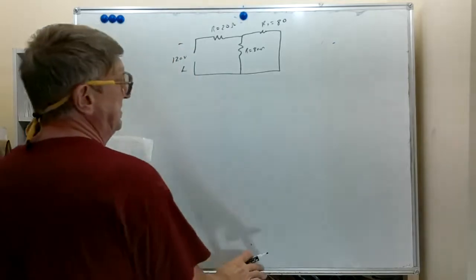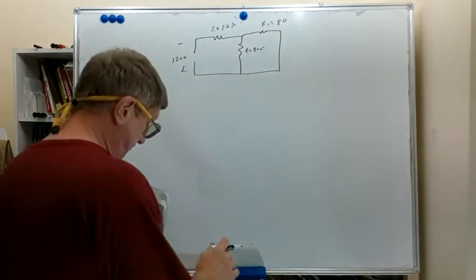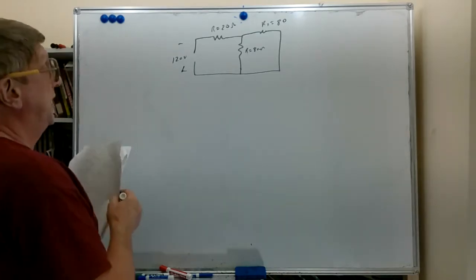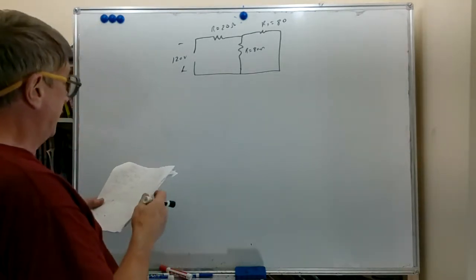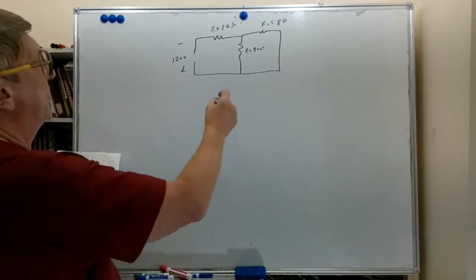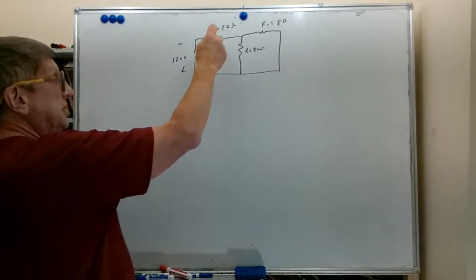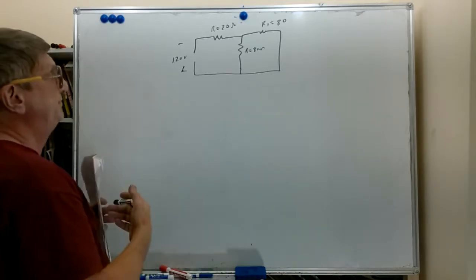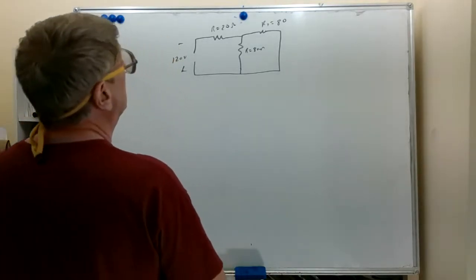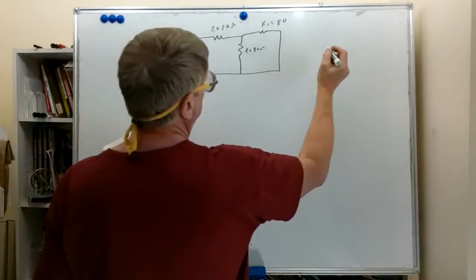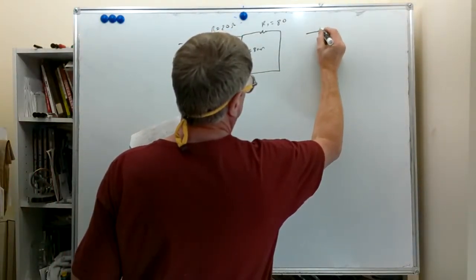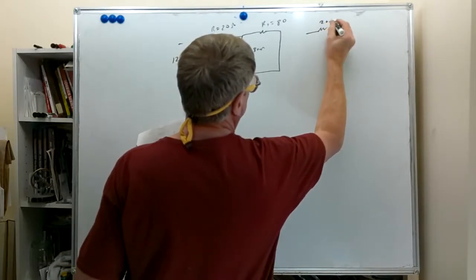So we've done quite a bit of analysis of these types of resistor network circuits with power supplies feeding them. This one has a series circuit in the main line. To figure out the total current, we need the total resistance. Well, we can redraw this as 20 ohms.